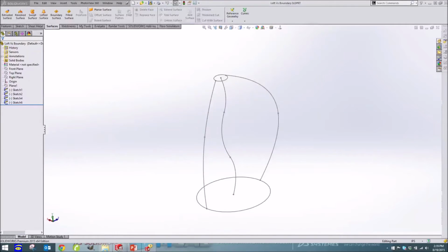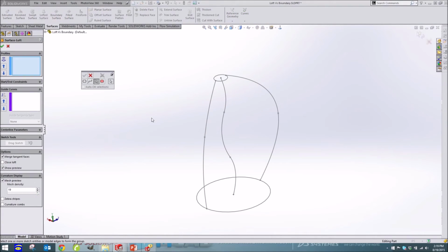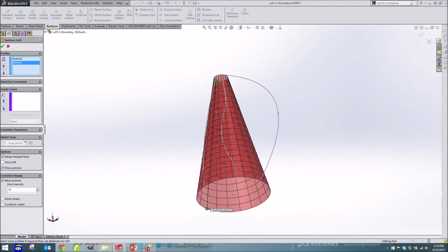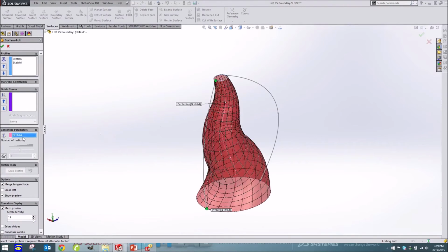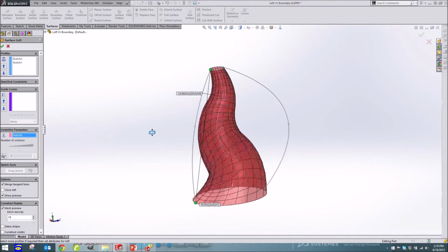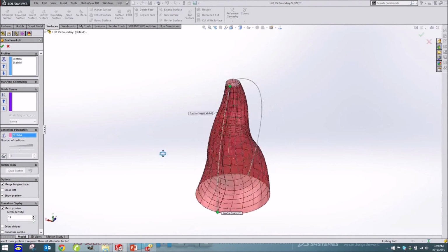All right, so let's talk about some of the unique abilities of a loft. Like I mentioned, lofts have a unique ability to add a center line. These are very similar to sweeps, but you can instead have two profiles at the beginning and end of the curve. Then using this center line parameter, you can have the loft follow along that shape.